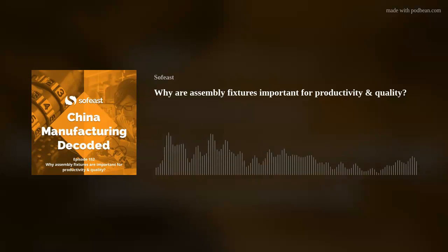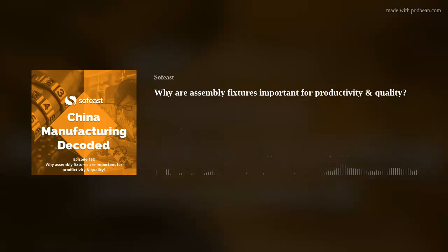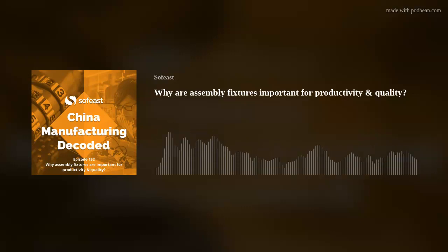There's this classic example of the IBM Pro printer, it was called, in the 80s. There were much fewer parts than in most other printers. And it was so simple to assemble everything from top to bottom, click, click, and everything assembled in 30 seconds with zero kind of fixture or any other tool. That's just amazing.